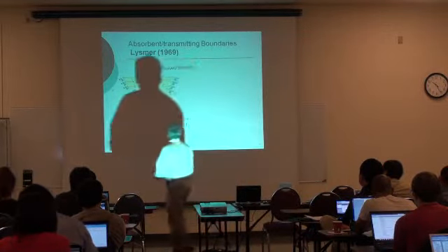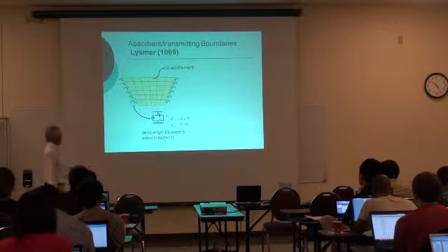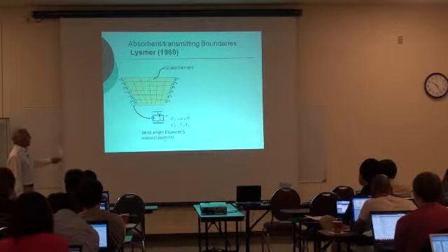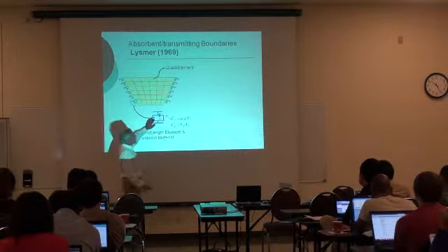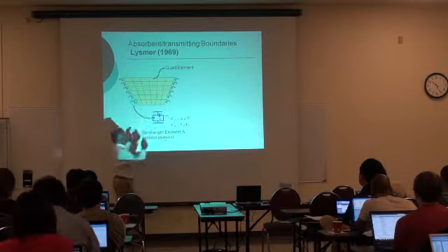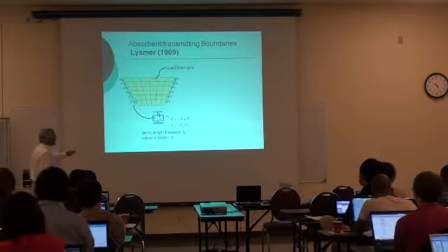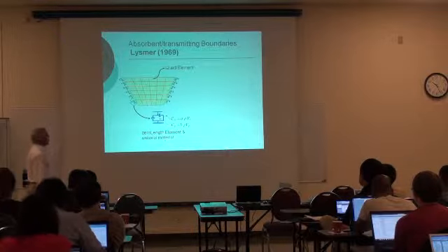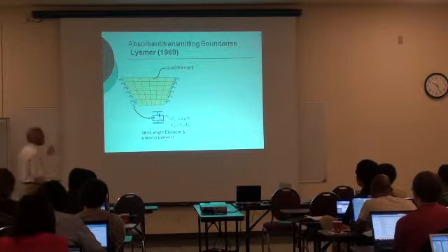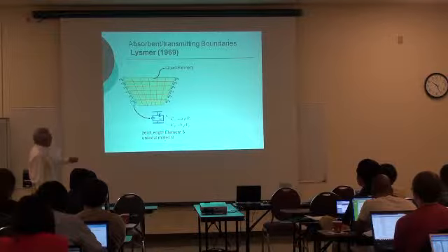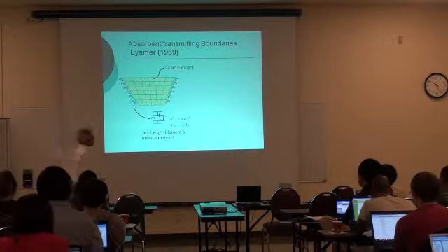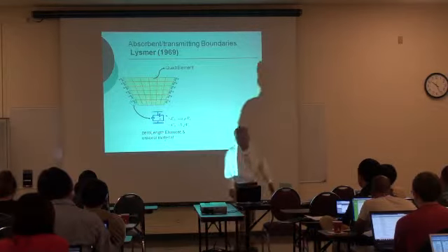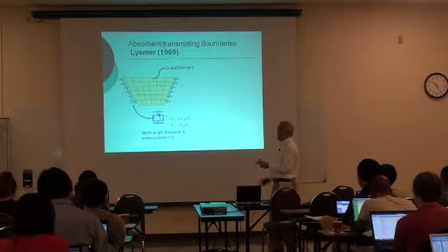And for doing that, what we use is, again, very simple zero-length elements and uniaxial materials, where we have these dashpots. If you specify the properties of these dampers or dashpots properly, they absorb the energy pretty well, in particular when the energy is normal, perpendicular, to the elements. These damper coefficients are based on the shear wave velocity, the P wave velocity, and the density of the material that you have there. That's the most common way of doing things.